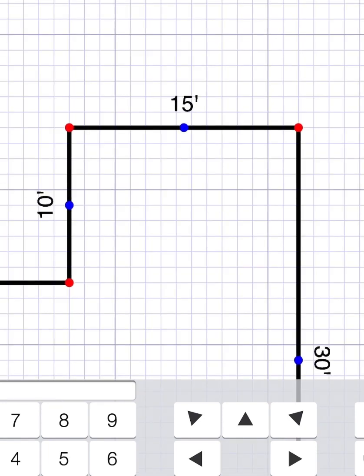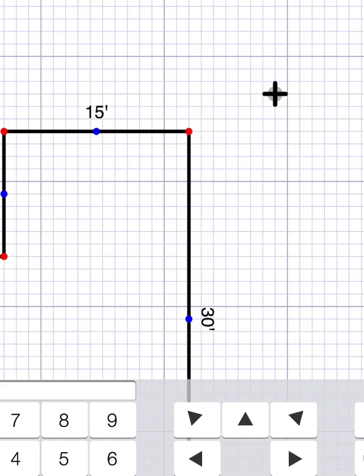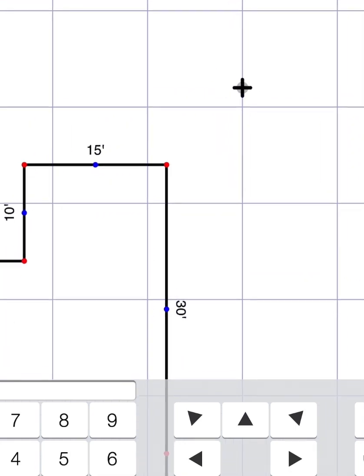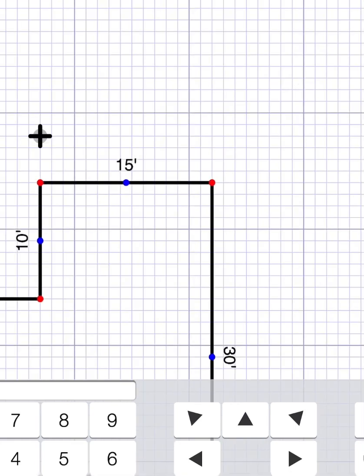up here, this 15, it's not going to be easy sometimes to use a laser measurement tool. A lot of times you're going to have to use a wheel for that because there's not really any backstop for your laser tool. Although if you do have a fence somewhere over here, then you could start from over here, use your laser tool over to the fence, and maybe that's 20 feet from here to there.